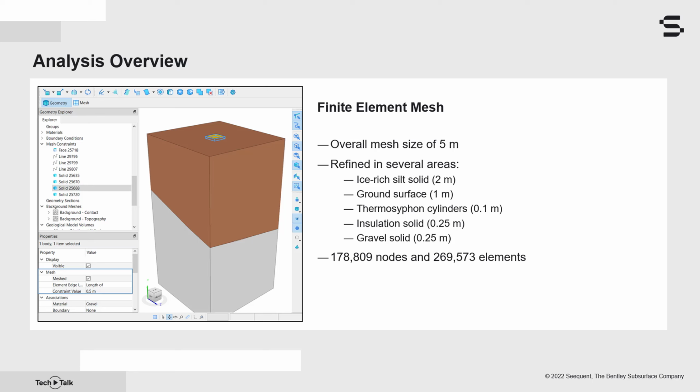Once the finite element mesh is generated, locations can be added in the mesh view. These locations are used for creating plots of the analysis results. We will review how to set up locations before solving the analyses. However, this step can also be completed after an analysis has finished solving. This means that if you wish to create graphs at new locations to better interrogate the model results, you do not need to re-solve the analysis after specifying the new locations.